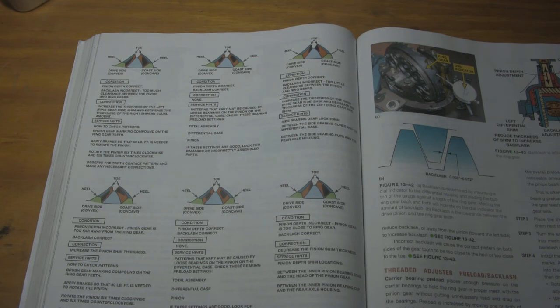And so if you pay attention to the shim packs and where they came out in the first place, and you put them back in the same place that they came out, 9 out of 10 times you're going to have a contact pattern that is correct the first time. If you have to make any modifications, you're going to have to tear the entire axle back apart, pull bearings back off, and a lot of times these bearings are one and done, and so if you press fit them on, you'll destroy the cage by pulling them back off to get to a shim, to change a shim, and so you can end up going through lots of bearings and causing lots of headache and frustration. But there are a few tricks, and in the videos, those tricks are going to be illustrated for you.